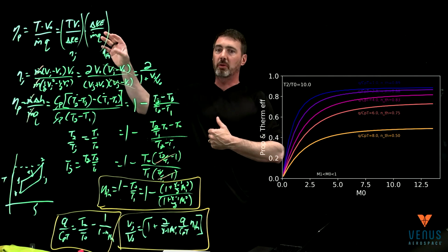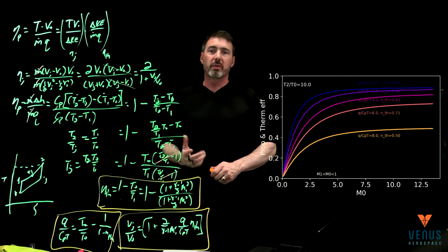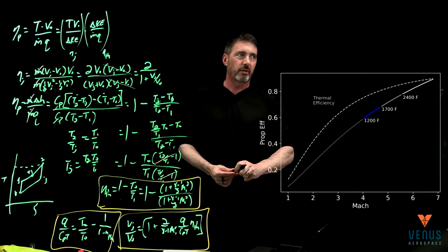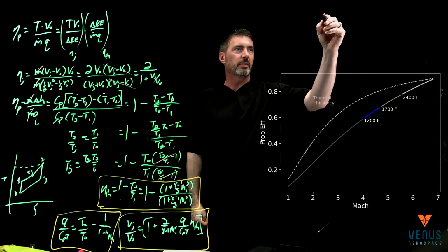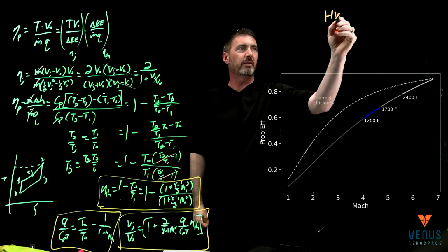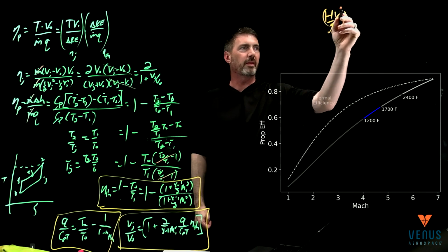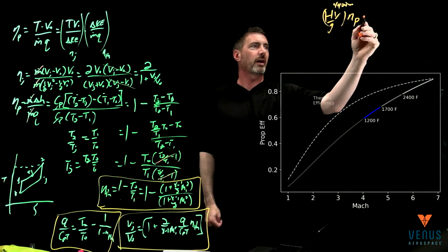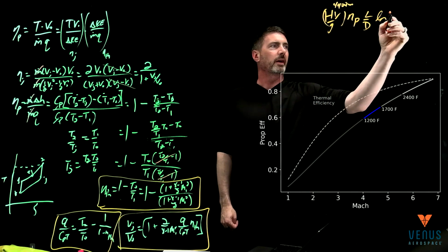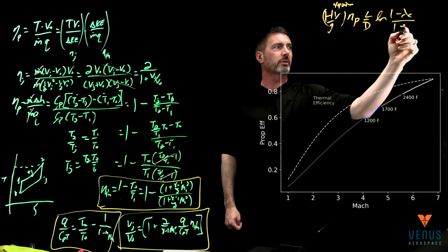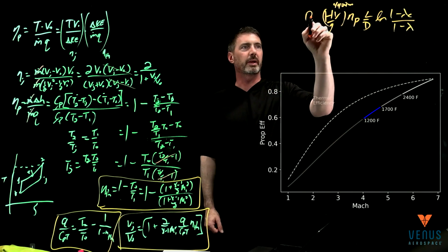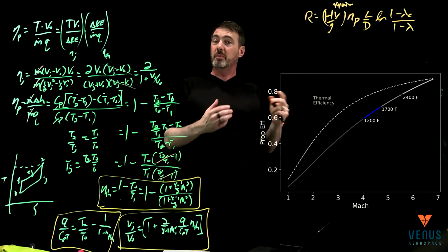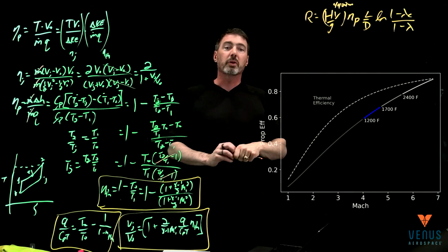Again, we have this propulsion efficiency, and we actually know that the range equation is going to be driven off of that. Writing down the range equation, that's the heating value over g, which I love in that form, but that's 4,400 kilometers, times the efficiency, times the lift to drag of the vehicle, and then 1 minus the amount of fuel I get up to cruise, and then the total fuel. So this is actually the range. And so we're building vehicles that go far.